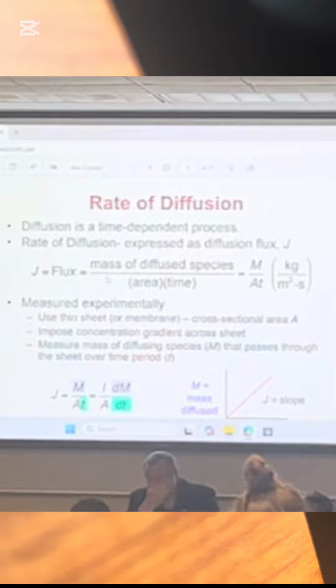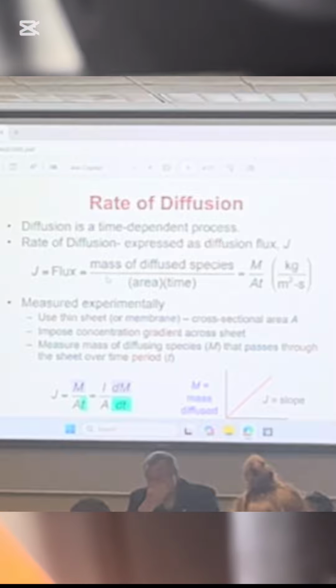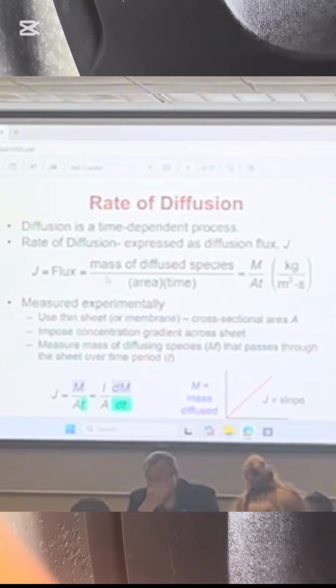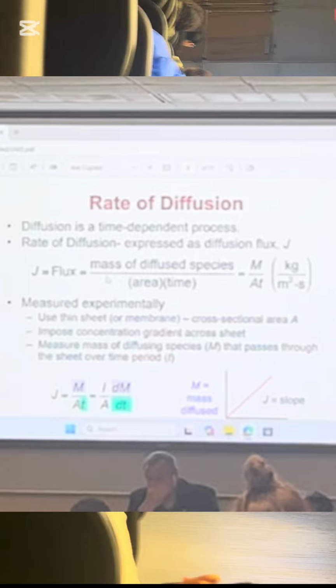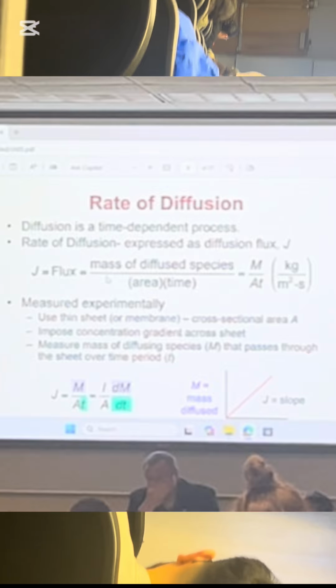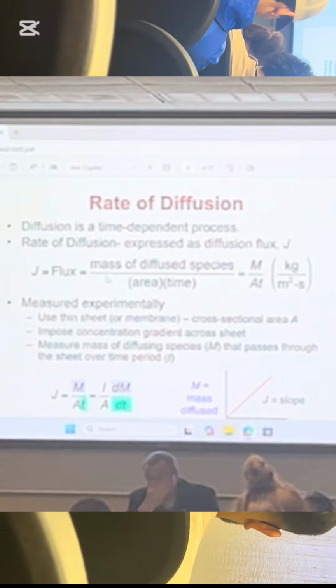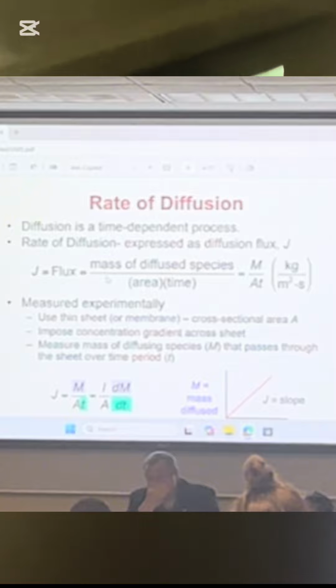So electron volts per atom or joules per mole. And that depends on what constant you use, Boltzmann constant or gas constant. It's the exponent of minus the activation energy divided by RT or KT. And the temperature is typically always given in Celsius. So you need to make sure you convert that into Kelvin for the calculation.